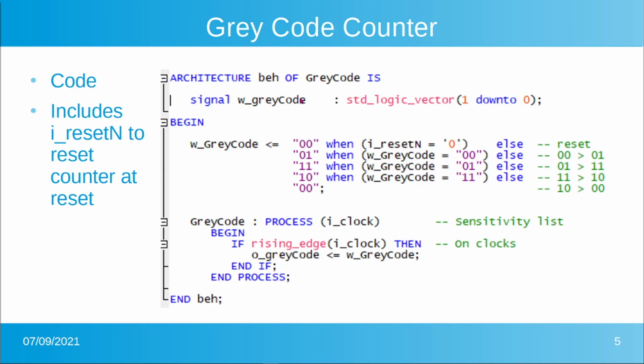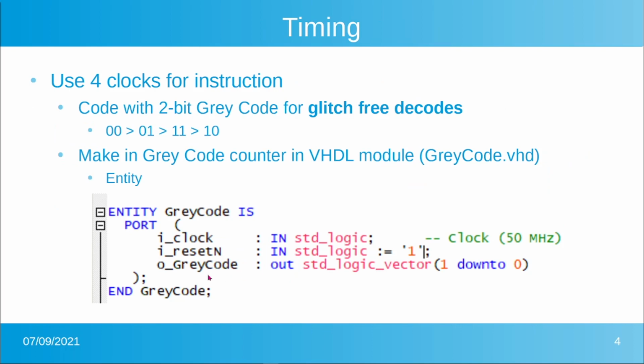We had to add a gray code signal inside of our gray code VHDL file with those 2 bits, standard logic vector. And we're creating, this is a little bit interesting the way this works, we're creating this element outside of a process loop. It could be created in a process loop, but this is that preload value, and then we're latching that value out. There is an error here that we'll catch, and the error is that this should have used the output gray code bits, and that also would imply, if we're using that, that this entity pin needs to be an in-out, not just an out.